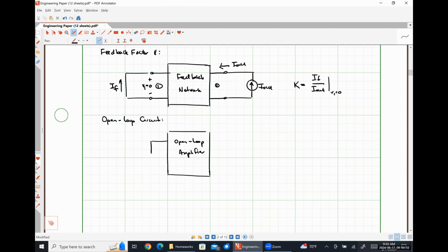We're going to have a resistance of R11 referred to the input side, a resistance of R22, sorry, this should be in series on the output side. Here is our resistance RL. Looking in here is how we find R naught, or the output resistance.